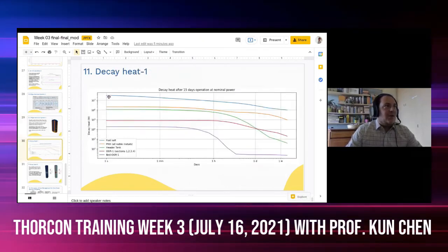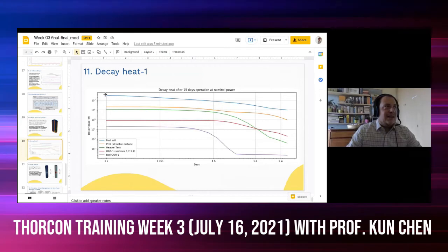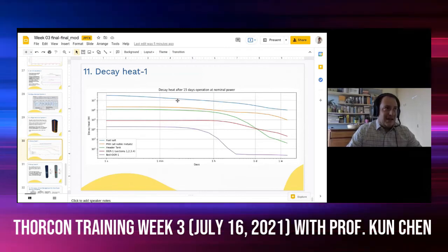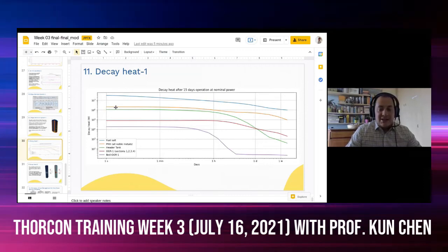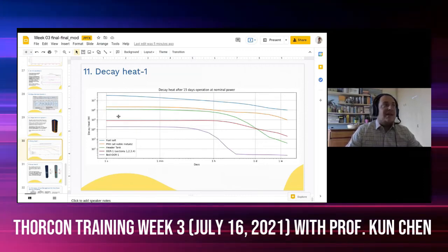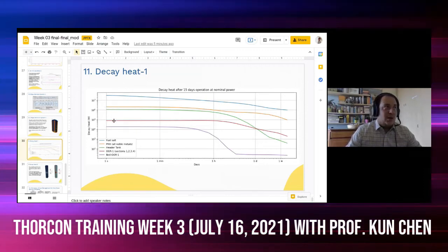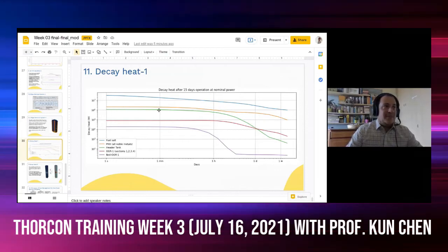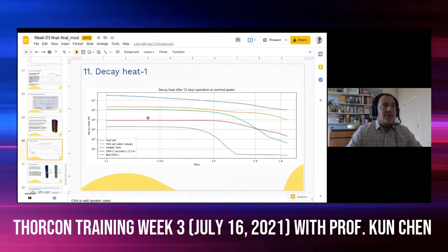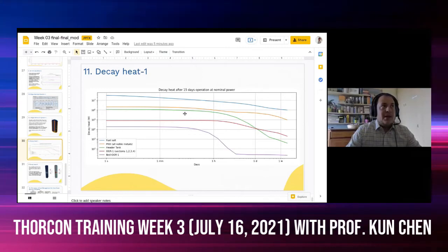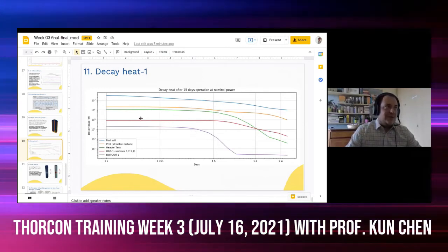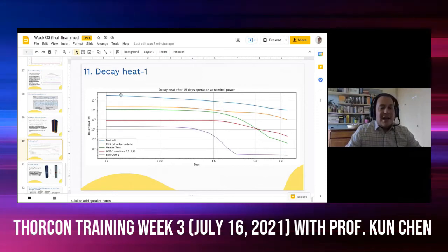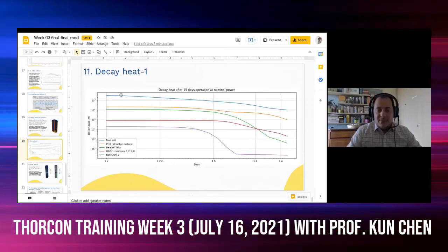As you can see, of course, most of the decay heat is inside the salt, but the decay heat rate in other components has to be analyzed and taken into account, as it might reach values above 1 megawatt in some components for the first few minutes after shutdown. This is the case for the header tank and the PHX.